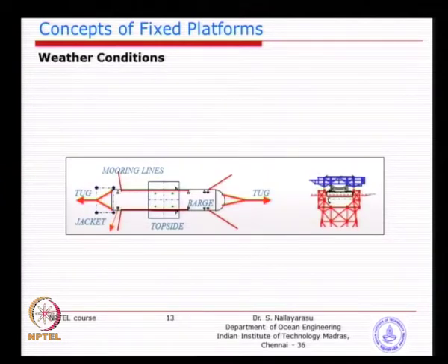The video you saw yesterday gives you a clear idea how the barge comes in and is pulled into the legs. What you see here in the picture, these 1, 2, 3, 4 are the legs of the jacket, which is already pre-installed, and there are 4 additional legs hanging on the topsides, and 4 additional legs in a little lighter color supporting the deck on the barge.